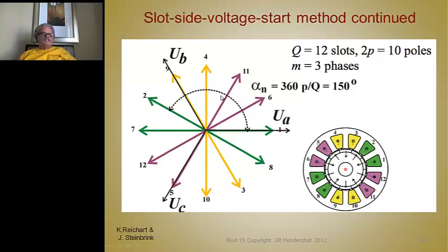So you count 1, 2, 3, 4, 5 of these slots. So that's why you number this slot number 2. So looking over here, here's slot number 1, there's slot number 2. Okay? So that means that we have to wind the first coil from slot 1 to slot 2. It goes across that tooth there. All right, now how do we find the first coil location for phase B? You count 5 again, 1, 2, 3, 4, 5, 150 degrees. So here is where you number slot 3.